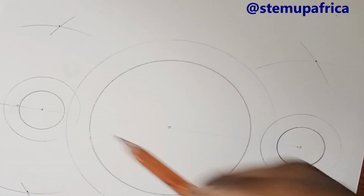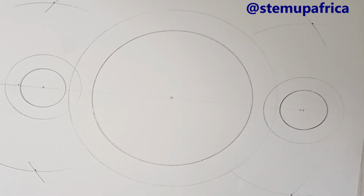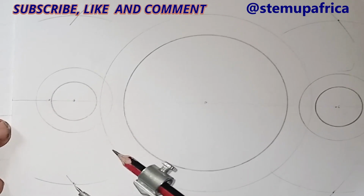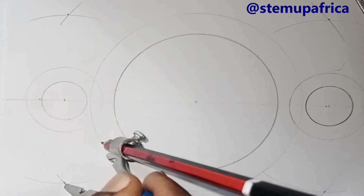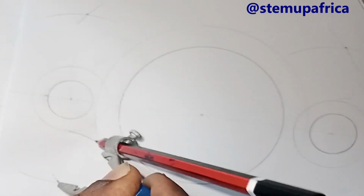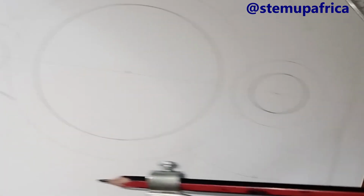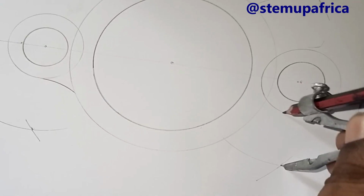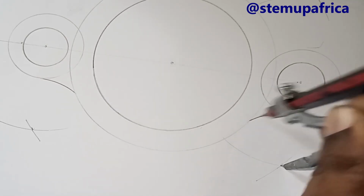With this point at center, I will now draw a curve of radius 33. So let's mark out 33 and draw. This is now radius 33. I'll put it where these 2 points meet, which is here, and draw a curve in this manner. See, it will just blend in perfectly. So I will do the same thing here. I'll draw a curve of radius 33. It just blends in perfectly.